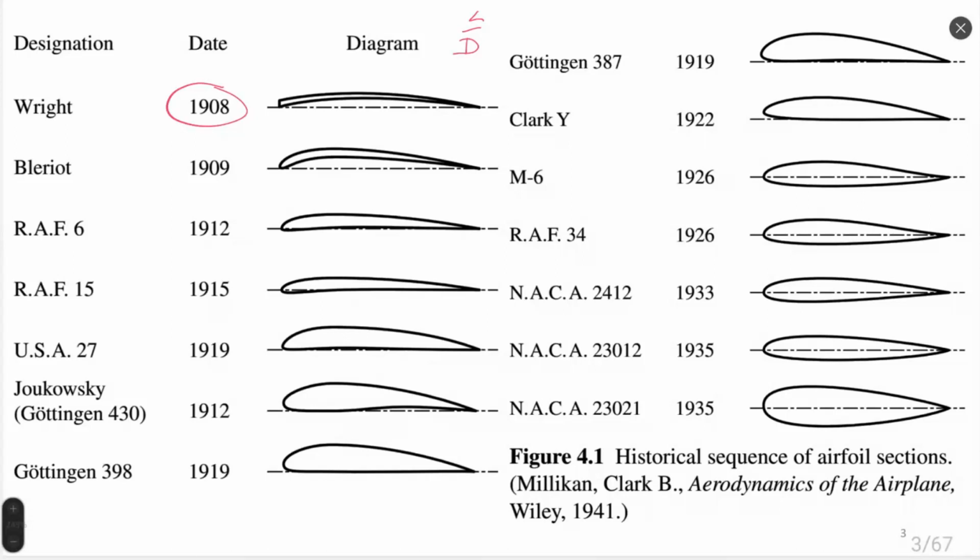Which are critical applications? First of all, people would like to fly as fast as possible. This is why a special type of airfoil called supercritical airfoils must be created. Supercritical airfoils allow us to fly very close to the speed of sound. The special shape of the airfoil allows us to decrease the separation region and to decrease the strength of shock waves created on such an airfoil. These airfoils also have a smooth shape, not a sharp shape.